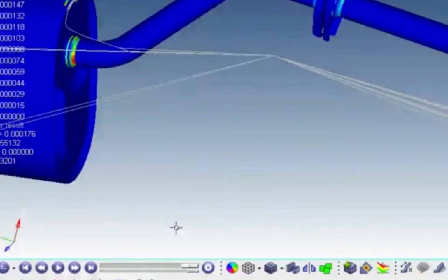Okay, I did it. Okay, so there we have the strains, the RMS strains, a maximum RMS strain of 0.000176. Now, just out of interest, the stress there was 220, so the Young's modulus is 200,000, so the linear strain estimate would have been 0.00011. So there's about 50% additional plastic response at that critical point. Now that in itself might be interesting to know how much plasticity is going on in your model at these notch positions. Other response statistics in here, we can plot the number of zero crossings.